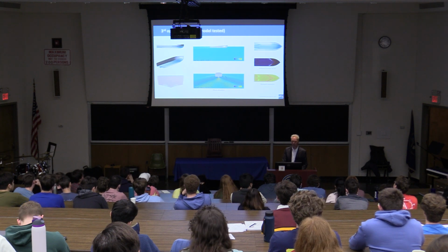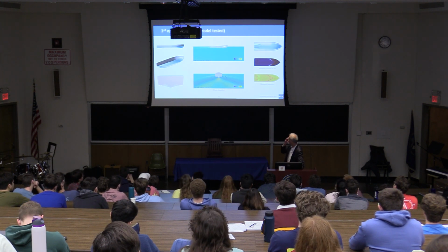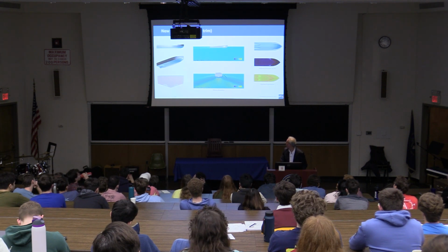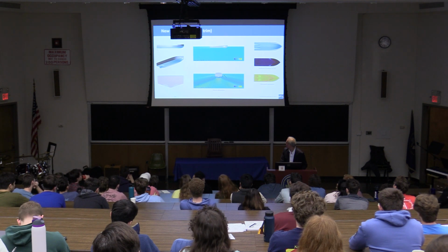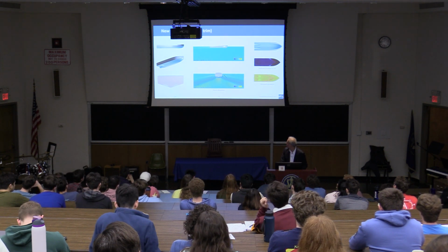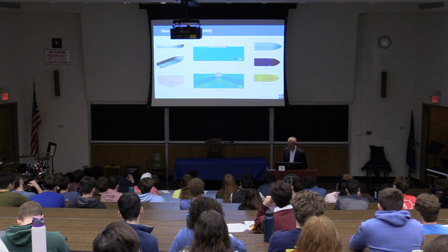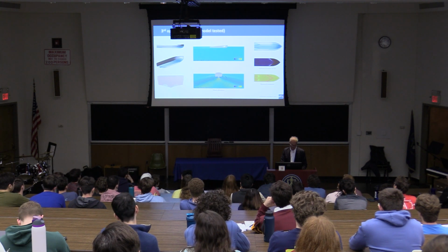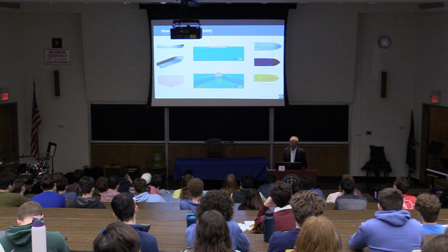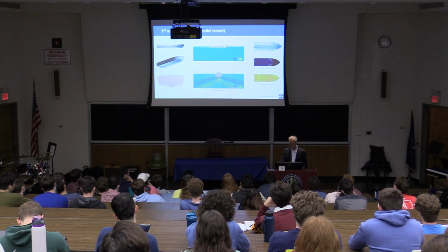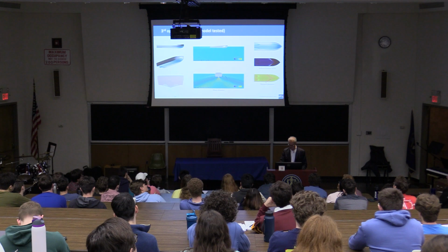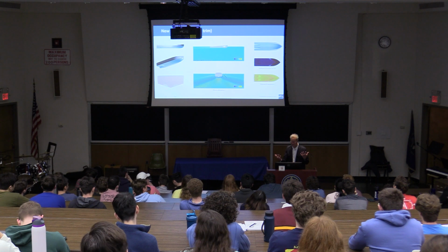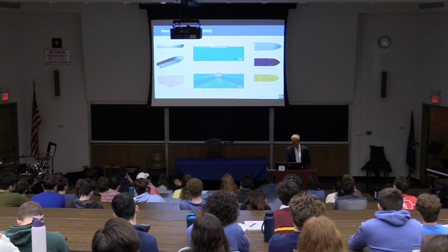And this is what we call the third optimized design. I'll go back and forth a little bit so that you can see the changes. Maybe take a look at the rocker over here. There's a rocker introduced, and also take a look at the deadrise when I change the geometry from the new baseline to the third optimized design. So there are changes in the geometry, changes in the pressure field, and also changes in the wave field, as you can see here, and this gives you the reason why we have an improvement.